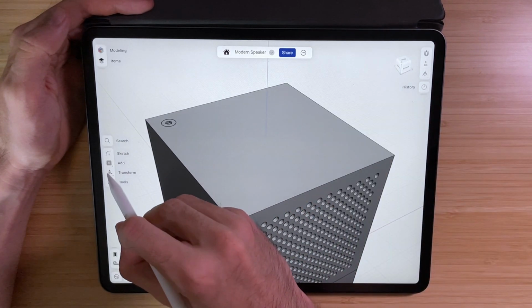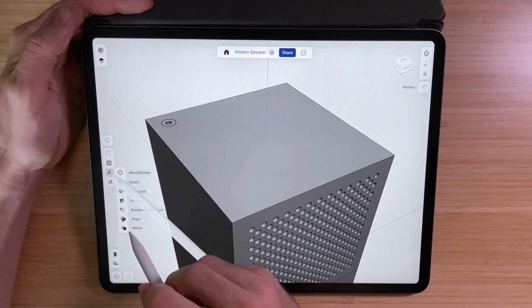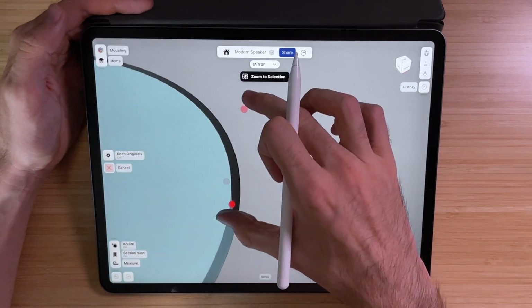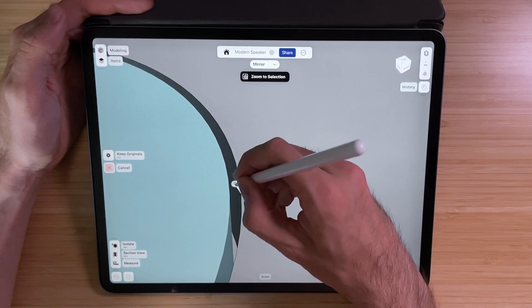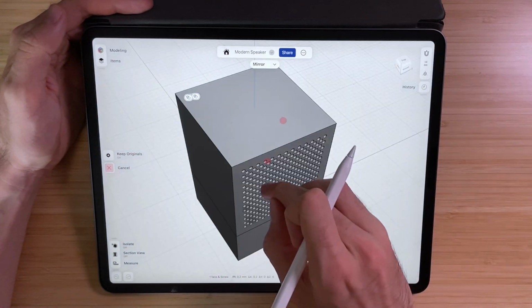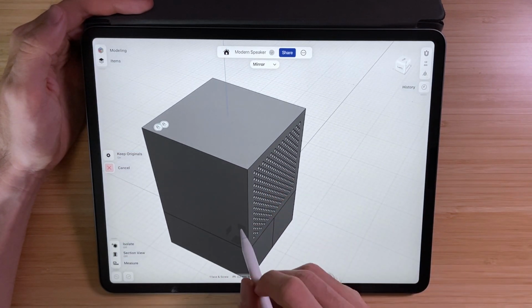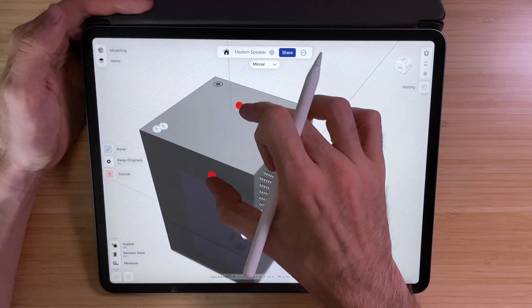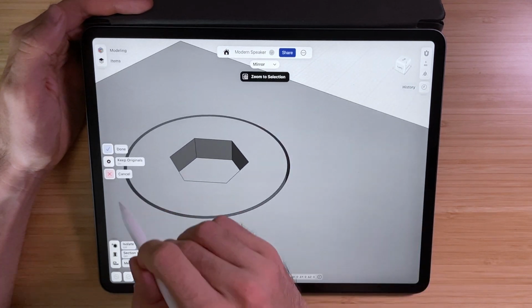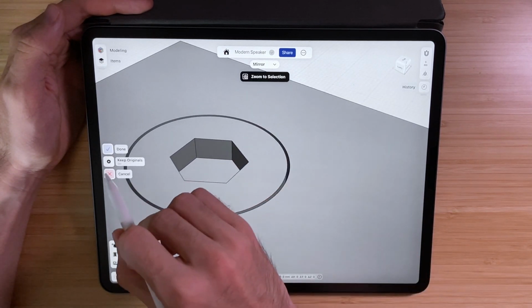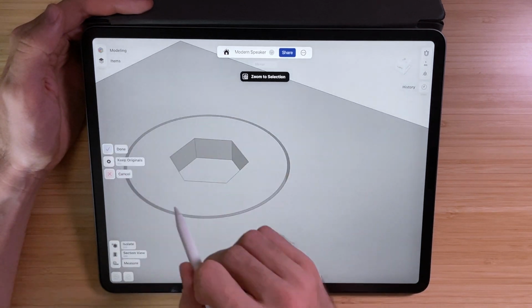So for the next part, we go to Transform, Mirror, select our screw, and also select the outer surface, so basically the cutting surface that we made. And now just zoom out where you can find this YZ plane. So it will mirror to one direction now. You can see if we zoom in, that looks perfect. So it already cut out with our outside surface, and put in this new screw.